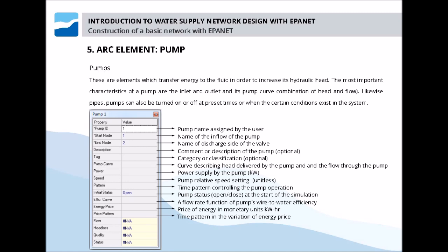The most important outlet parameters are water flow and load. Water flows in one direction inside the pump, and EPANET does not allow one pump to work out of the range provided by its own curve. The speed variation of pumps can also be taken into consideration, and be determined and modified under the previously described conditions.